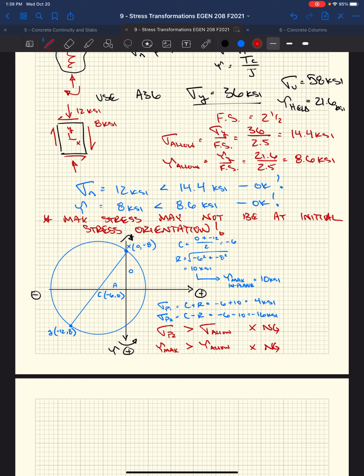So even though somebody probably has or will in the future stop here in their analysis, hopefully the factor of safety will overcome that. But that's not a recommendation either, right? It doesn't say that you can just cut corners like, oh, 2.5 will cover it. I'm just telling you how scary it is in the real world that that happens. And fortunately, factors of safety do kind of pick up the slack.